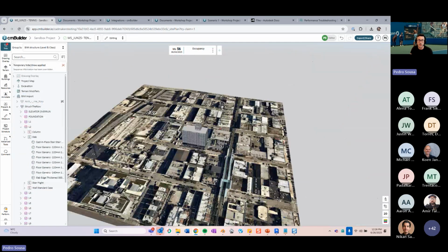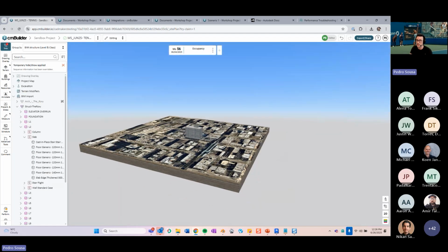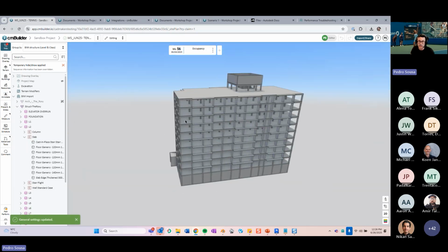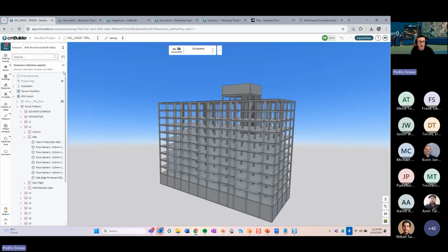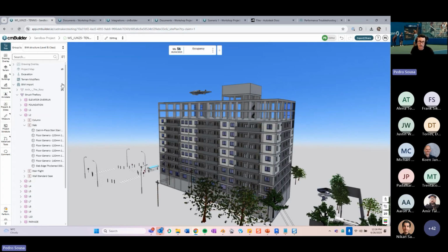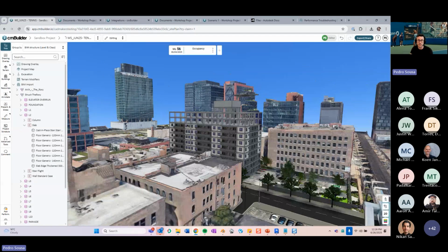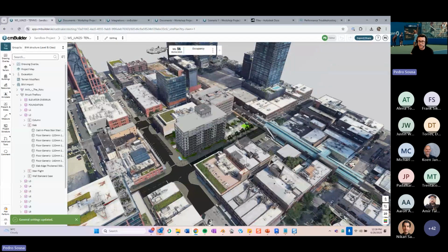So all the other parts of my view are going to go away temporarily, minus the terrain, because the terrain is above everything else. So you need to hide the terrain on your own by clicking on this button over here. Okay. And then once I am done working with this model, I can go and click on this guy. But again, the terrain is not going to come back. So you can click on show to bring back the terrain and work with that within the context. Okay.